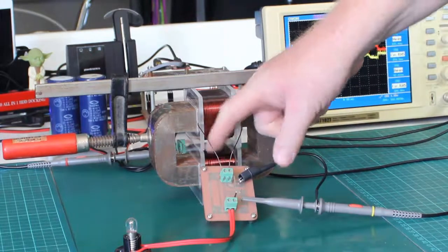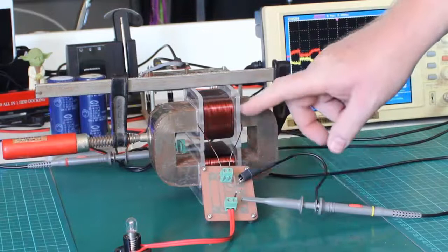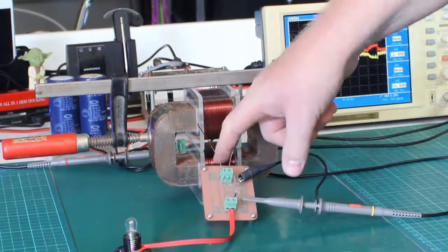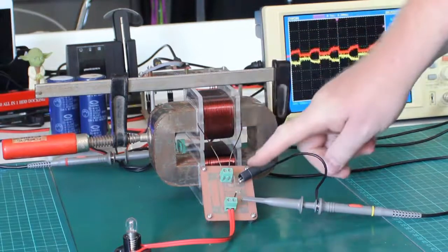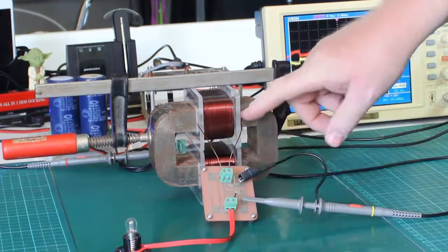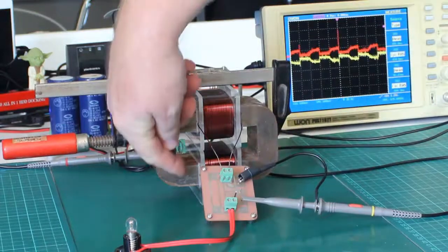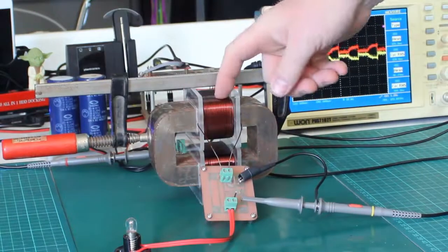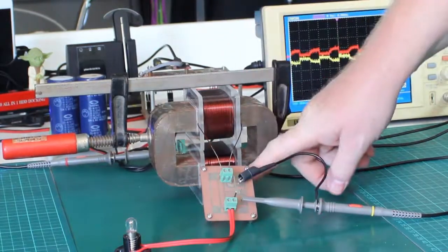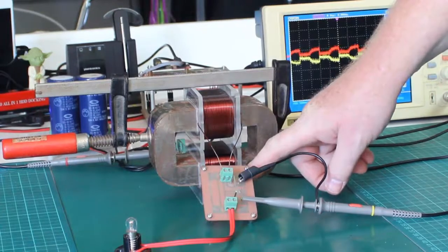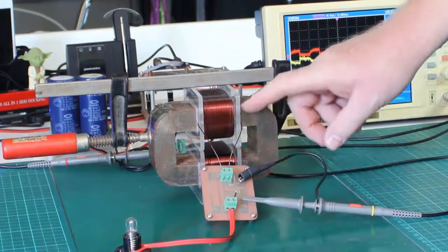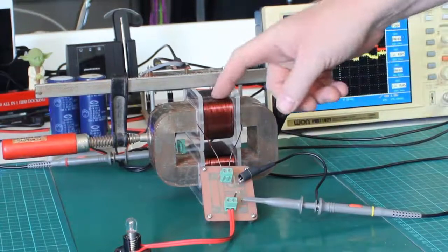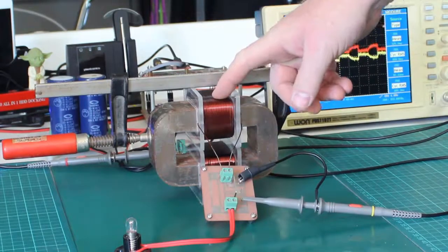So the coil down the bottom is sending a current. Well, the current is climbing in the coil, but the magnetic field is moving around the core like this. Okay, both sides. The top coil sees the change in magnetic field. So the magnetic field in the bottom coil changing in time through the core is what the top coil sees.